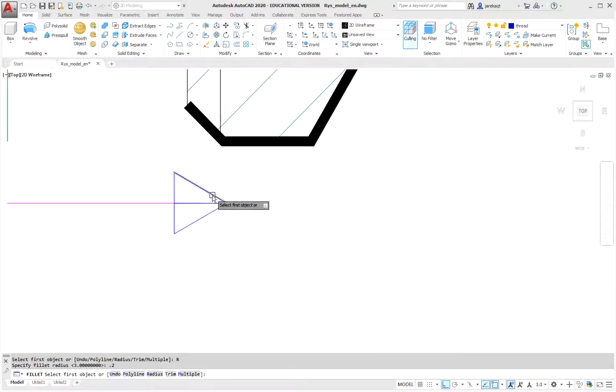And we'll say we round here. From this outline a solid must be created that will be dragged along the helix, but for it to be formed it cannot touch itself. Therefore we will shorten this triangle by 0.1. This is sufficient for most thread cases.